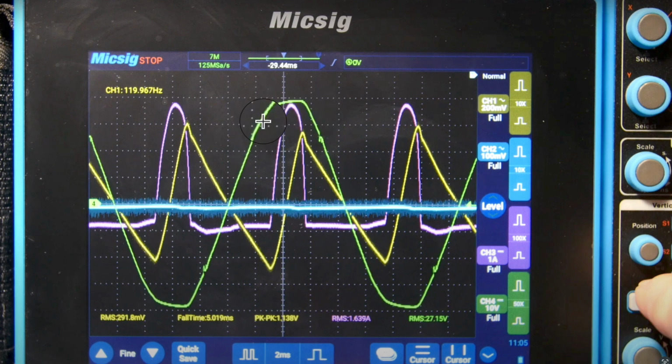That DC resistance has a voltage drop, which is what we're seeing here. So instead of coming up like it should, there's a voltage drop and it flattens off. But you notice how it slopes up a little bit? That's because the current peaks right here, in the middle, and then as it starts to drop, the waveform starts to go up, okay? That's what's happening there.